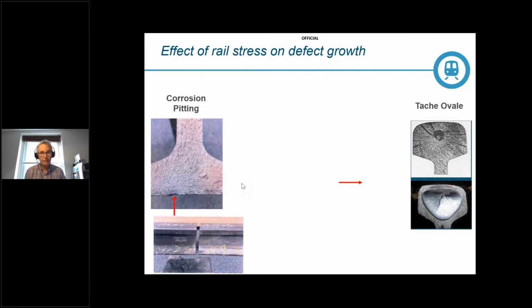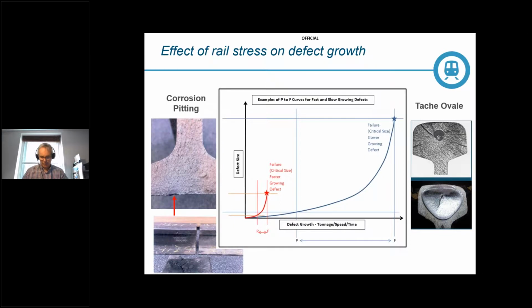Things like these are actually dominating rail failures now. The left-hand side picture shows a rail that has failed from a fatigue crack from a corrosion pit in the foot. Note how small the crack is. This type of failure is often driven by poor track geometry associated with poor support, and often occurs at locations like the run-on or run-off of direct fastening bridges, or where poor support conditions pertain for an extended period of time. So what's that telling us?